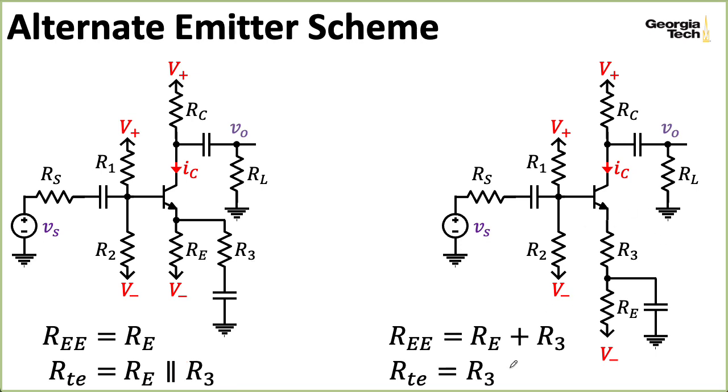On the other hand, in the circuit on the right, R3 sets the gain, but it also plays a role in the bias. So you can't adjust this R3 without also changing the biasing, which I guess also can affect the gain. So it's just a lot more complicated to deal with if you're trying to adjust things. But if you're just fixing a few resistors, good enough.